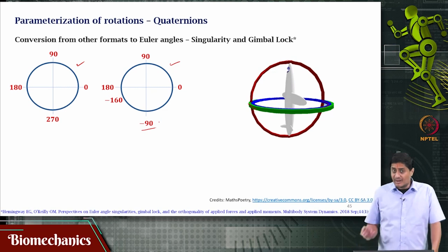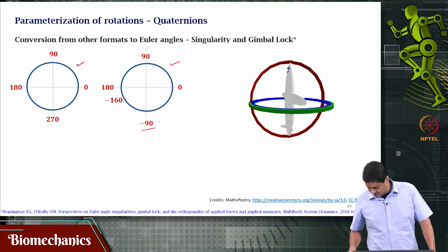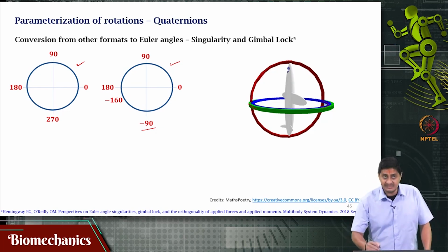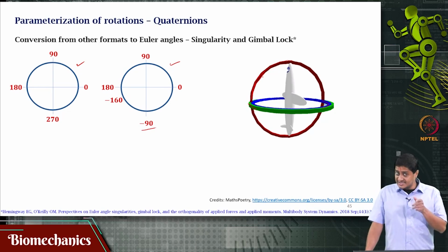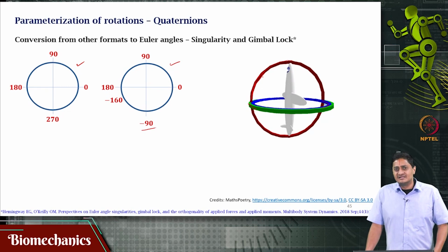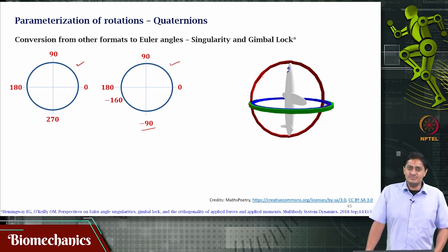This gimbal lock would happen when the brown gimbal reaches 90 degrees. So, when you are getting close to 90 degrees, say 80, say 75 onwards, you have a control mechanism that prevents gimbal lock from happening. But somehow that did not work. For some reason, the control mechanism that was present to avoid the gimbal lock also did not work.